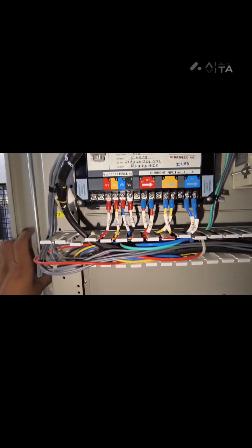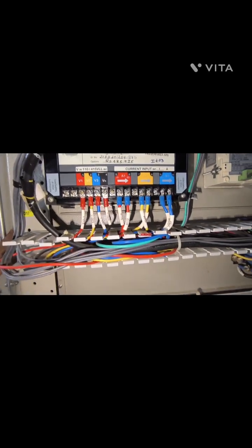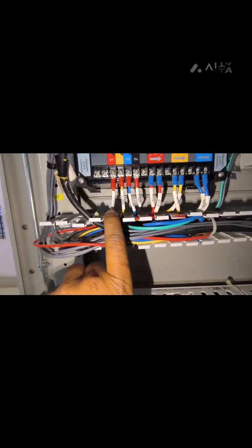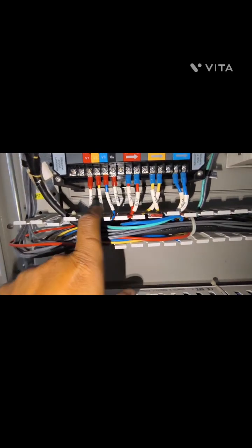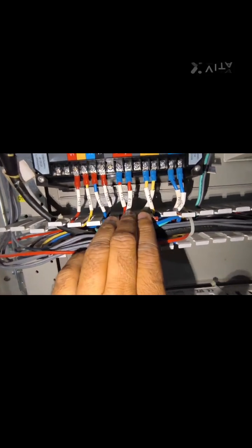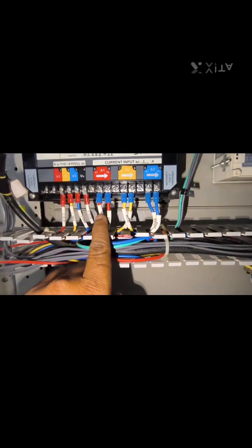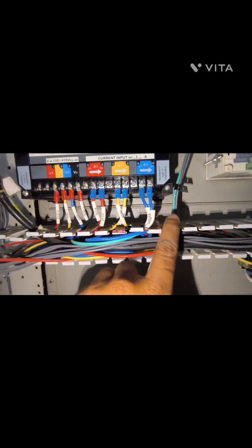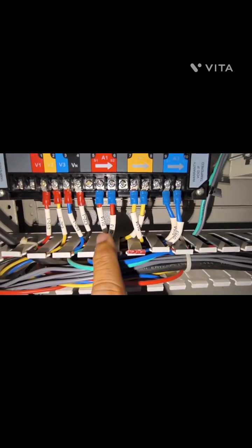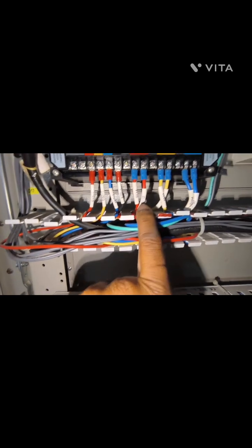This is an MFM, or multifunction meter. You can see here, this is the PT supply given here. The Ferrule starts with E. So these are all three PT supply. This starts with D, that is the metering core. You can see D113, 114, 34. This is S1, S2, S1, S2 like that. So these 6 cables belong to the CT. So it starts with the metering core CT.